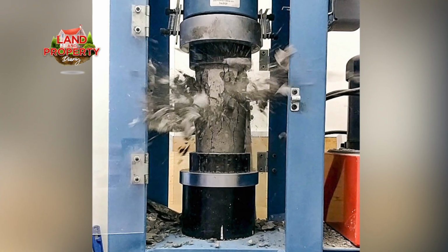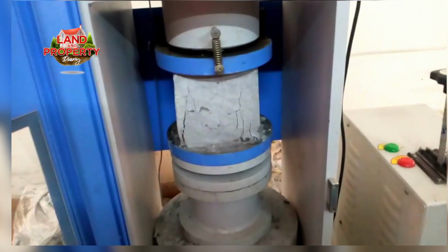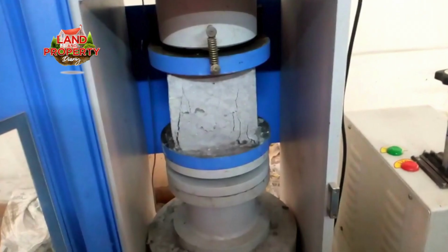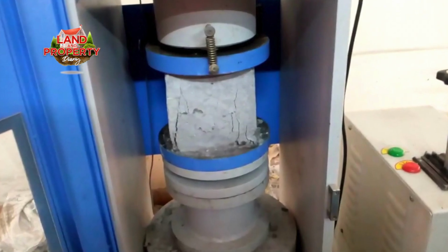At the point of crushing, the loading versus the area of that cube is taken, and then you get the compressive strength of that particular cube. That strength acquired is what we expect of that mix at 28 days, to have attained 10. So we have 10, 15, 20, 25, 30, 35, even up to 60, depending on where you are going to use this concrete.